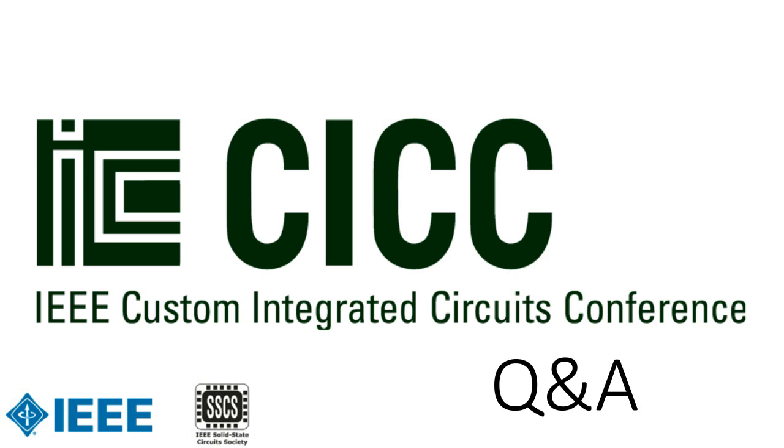Right. Unfortunately, all our prototypes were not in FinFET processes, so I cannot provide too much information on that. But our experience is that even in the bulk technology, we don't know how much noise is coming through the substrate. That's why if you check our approach, we always have some kind of adaptive loop to learn that coupling path. So to us, it's just a black box, some kind of unknown path. What we are trying to do is to learn what the transfer function looks like, and then how we can cancel it out. And that'll be the answer.